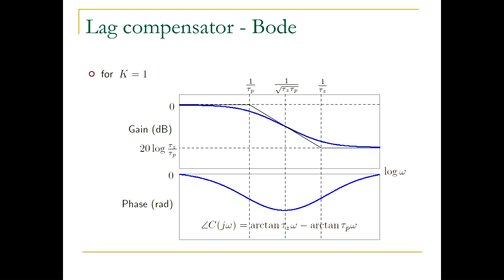So we already saw how k affects this Bode diagram. So k larger than 1 will shift the magnitude plot up, and k smaller than 1 would shift the magnitude plot down without changing the phase. Now what happens if we stretch these corner frequencies? Well, this bump will go lower, right?